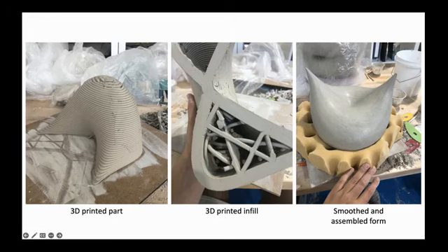So the first summer I used Cura to slice these parts up and print them. I printed them with lots of infill because they were rounded and had lots of overhang angles, so they needed support from the inside. The toolpaths and infills were all generated by Cura, which wasn't designed for clay 3D printing, and so sometimes some of the toolpaths didn't quite make sense with the material of clay. Since clay is malleable and can be hand worked, I made it work with this slicing technique.